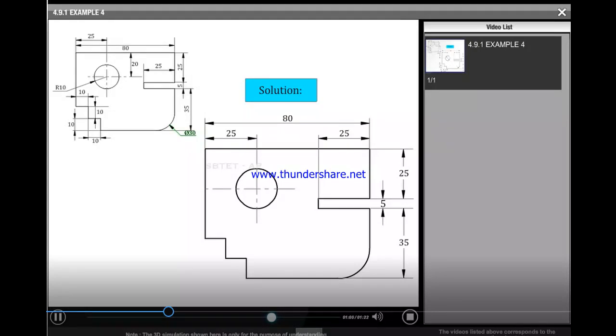So in the question, it is given that 20, 25 and 5 are inclined. The representation is inclined; 35 is inclined. So it should not be represented like that. All the dimensions above the dimension line are to be placed vertical. That is the main observation in this example.